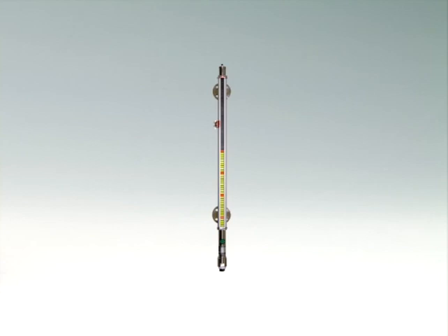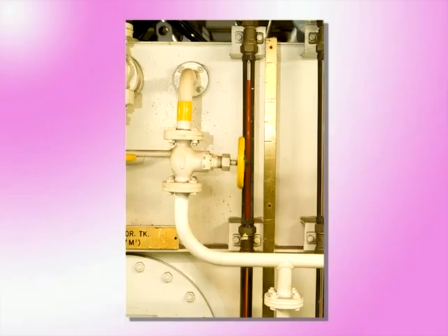It is always necessary to know how much fuel oil remains, and whether or not the proper quantity of water has been supplied to the boiler. It is also necessary to know exactly how much crude oil or LNG has been loaded or unloaded. For these reasons, level meters are installed in most vessel tanks. The level meter is usually a glass tube connected to the side of a tank to allow for measurement by sight.